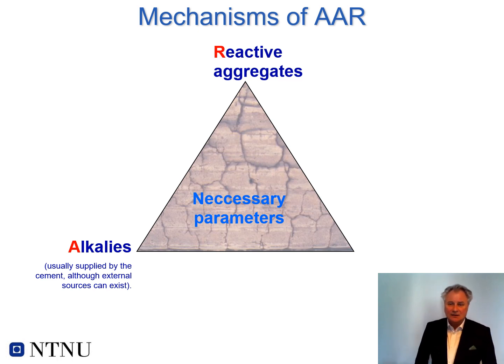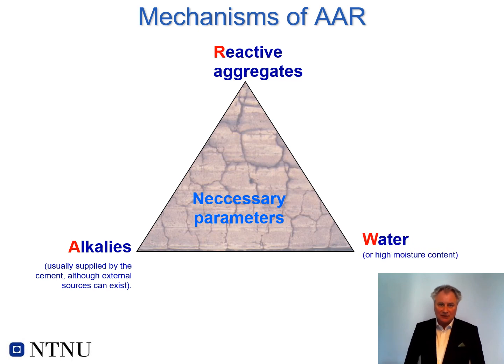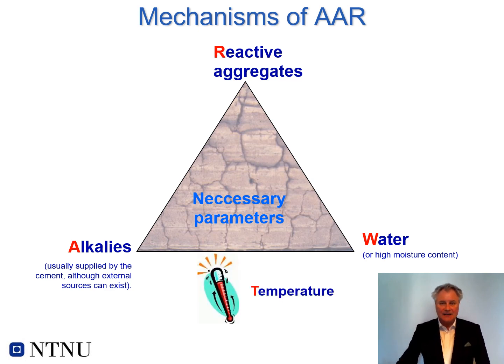And also recently we have realized that the aggregates themselves are releasing alkalis that could contribute to the reaction. But in addition to those two, we also need to have the third component, which is moisture or water. And all of this will be accelerated by the temperature.